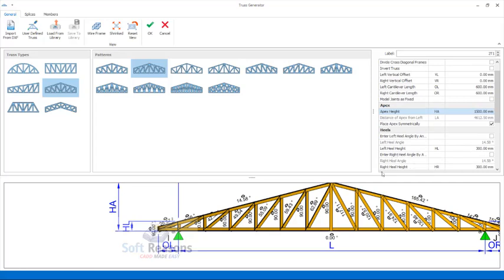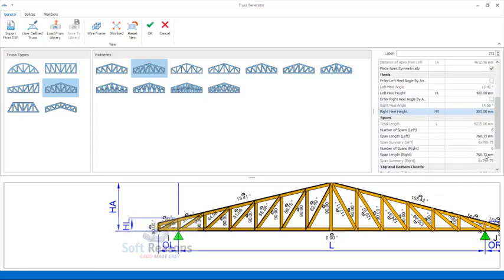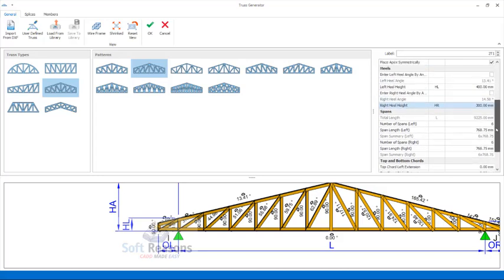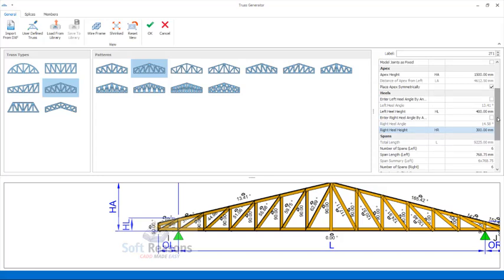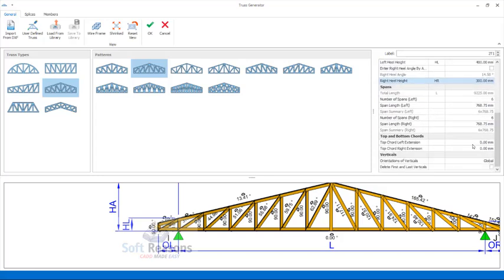We wouldn't have the left eave height again. So this will enable us to increase the head height right here from 300, let's say 400 thereabout, and see. Okay, we have some head height. Okay, that serves as our fascia. Okay, so we proceed to change this other side to 400 as well. Okay, that is the right head height.